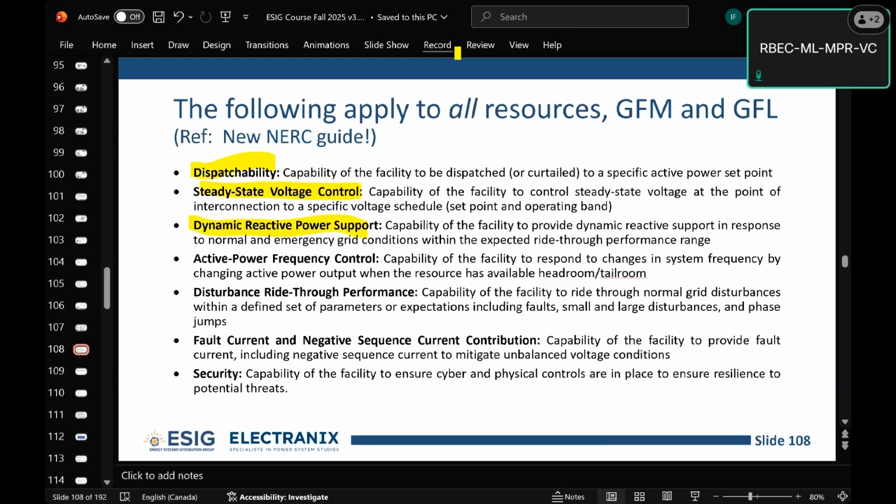Okay, so all of that natural imbalance that we have in the system from unbalanced loads, from untransposed transmission lines, all of that is coming home to roost because all of the synchronous machines that were basically soaking up that unbalance are being retired, and we're left with devices that don't do unbalanced control in steady state. So the unbalance is rising in the system, which is potentially going to start hurting synchronous machines again. When you add grid forming resources back in, and we found this kind of by accident in Hawaii, that starts to soak up unbalance again.